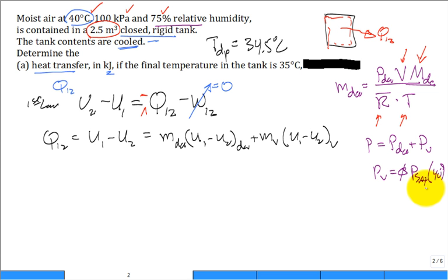Yes, sir. Do you also use the volume from the dry air, or do you use total volume? Okay, that's a good question. This is the total volume. All questions are good. But it's the total volume, because it's the partial pressure concept. You go back to Dalton's model, it was as if it's all at the same temperature and volume of the mixture. You're right. No, don't mix and say, well, I have a partial pressure, maybe I need a partial volume. No, no, no. Either go with Dalton's or Amagat's. And typically we like partial pressures.